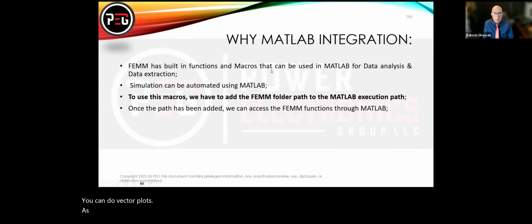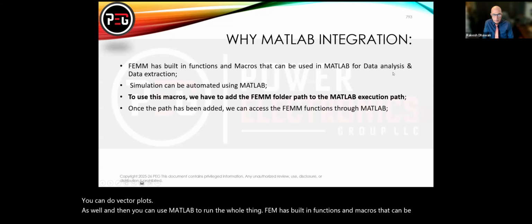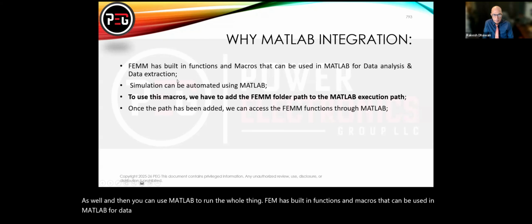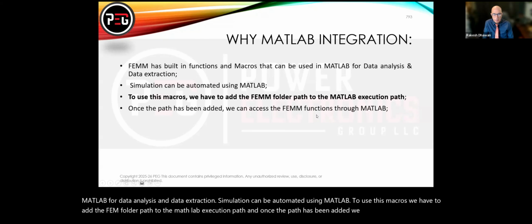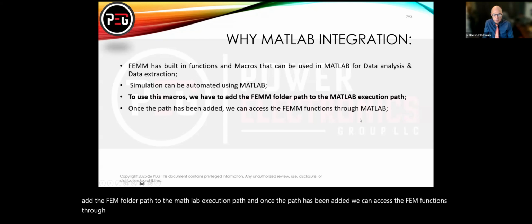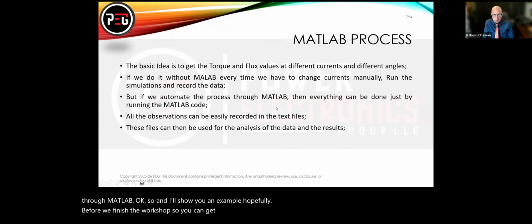And then you can use MATLAB to run the whole thing. FEMM has built-in functions and macros that can be used in MATLAB for data analysis and data extraction. Simulation can be automated using MATLAB. To use these macros, we have to add the FEMM folder path to the MATLAB execution path. Once the path has been added, you can access the FEMM functions in MATLAB. I'll show you an example, hopefully, before we finish the workshop, so you can get an idea.